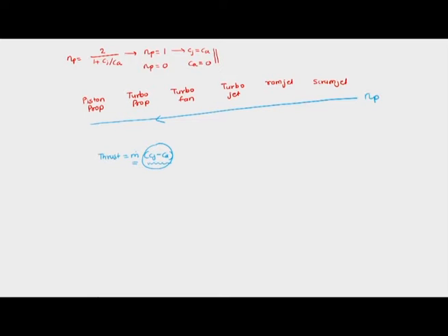If the value of Cj minus Ca is large, then propulsive efficiency decreases. If the jet coming out of the aircraft has a very large velocity compared to the aircraft velocity, those aircraft would have lower propulsive efficiency, and that is the case with scramjet, ramjet and turbojet, and also turbofan. These aircraft have a jet velocity much higher than the velocity of the aircraft or the air coming into the engine, and they handle a lower mass flow rate of air compared to the other engines.